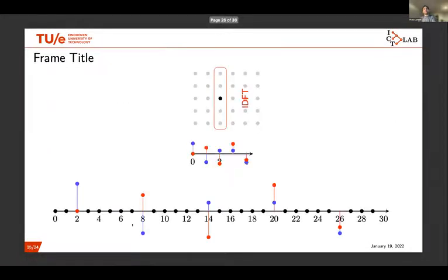So we can also define different points here in the Zak domain. For example, if we define here now a point which is at k not equal to 0, this will give us then a modulated signal. So for example, here the blue indicates the real part of the sequence, and the red indicates the imaginary part. And this sequence is then also again spread. We see here the starting index is 2, because 0, 1, 2. We start here at 2, and we start spreading the sequence.